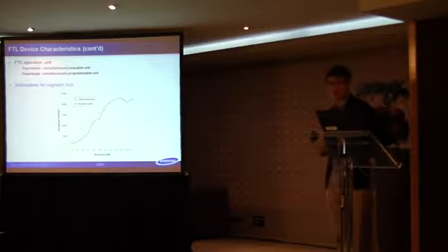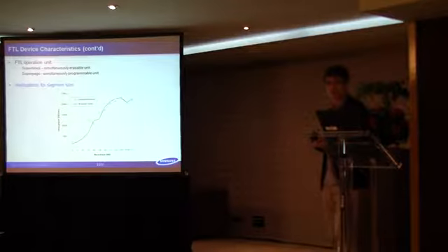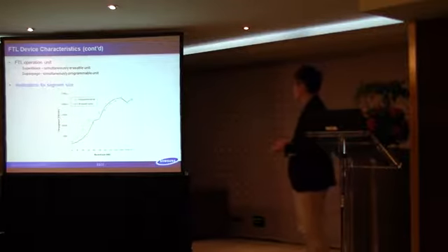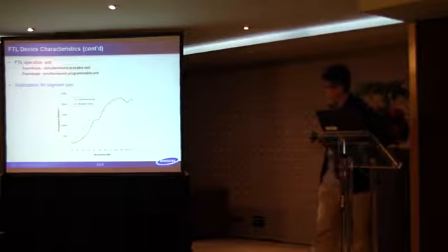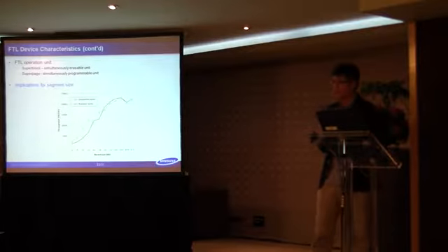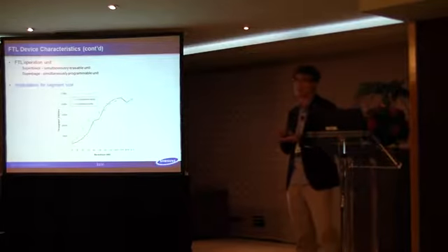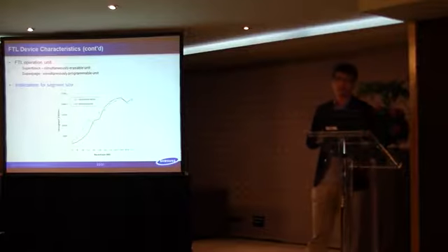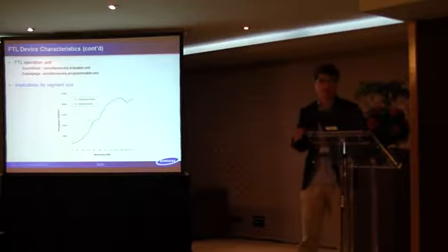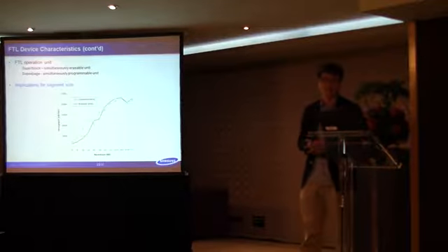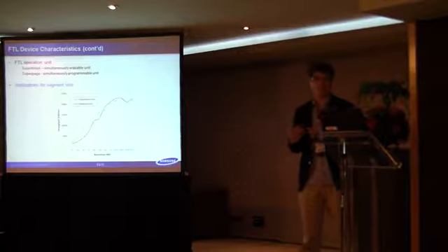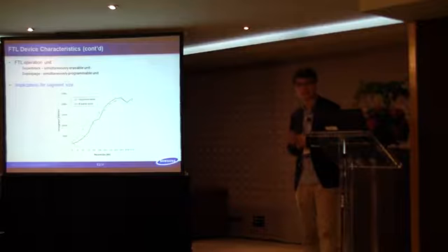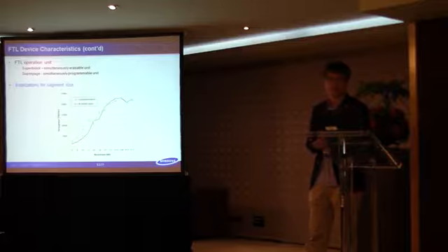And FTL has a super block and super page geometry unit. So super block is a unit size for the simultaneously readable size. And super page is the simultaneously programmable unit. Because we have many NAND flash chips inside the eMMC, the embedded controller has many channels for the parallelism of those NAND flash chips. The controller programs multiple NAND flash pages together, so that enhances the bandwidth.